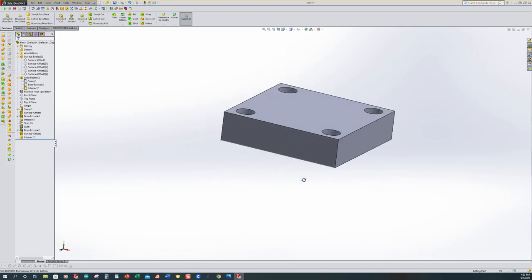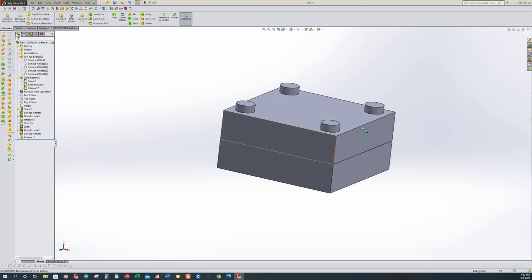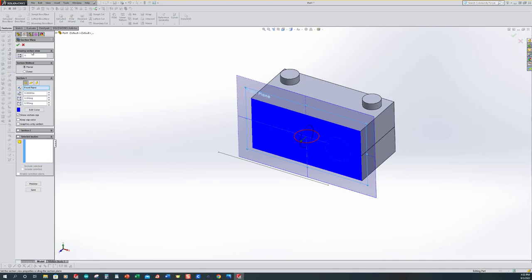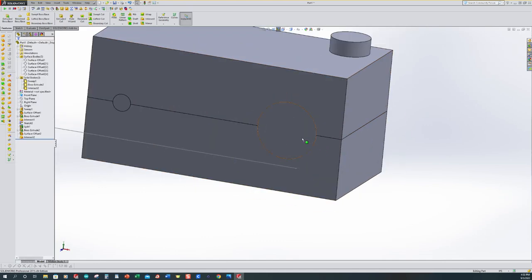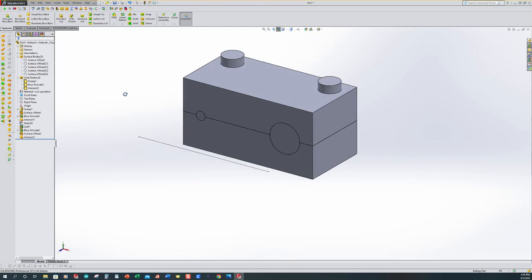So now our upper mold and our lower mold, one of them should have pins, one of them should have holes, and then we also have the sweep that's in here as well. Alright, so let's cut this thing in half and take a look and see what's going on in here. Alright, so our body is split here. There's where the earring would be, and these are where the ejector pins would be in our mold. Alright, so I'm going to unselect this.